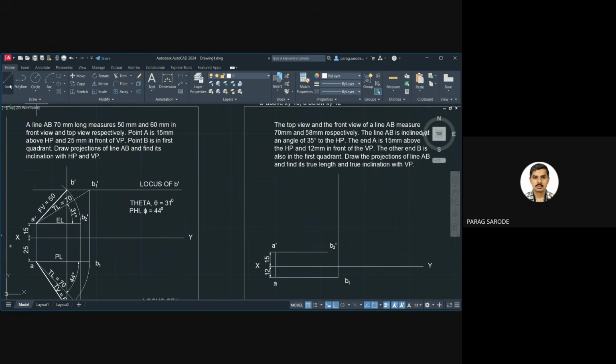So now with the line command, we will take A dash as the center because we know the true length should start from A dash. Now we will switch off the ortho mode, and we know that on this line we are going to get B1 dash, correct? We don't know the length, but by just crossing, you can see some length, something like 97.5969, correct? Yes, sir.